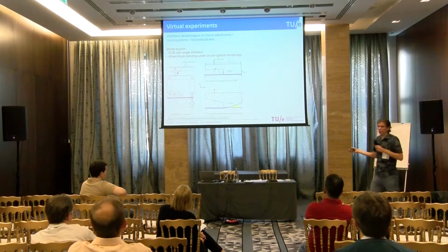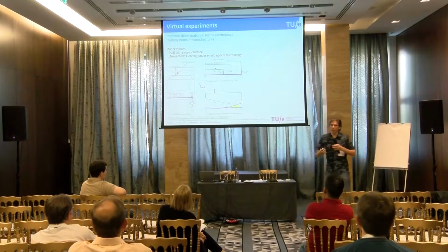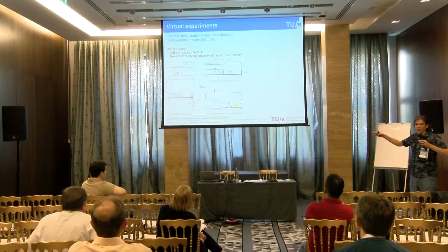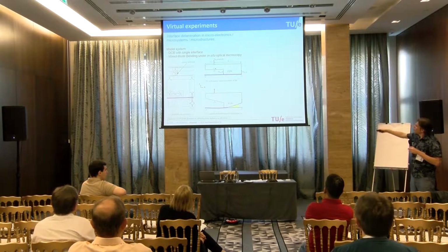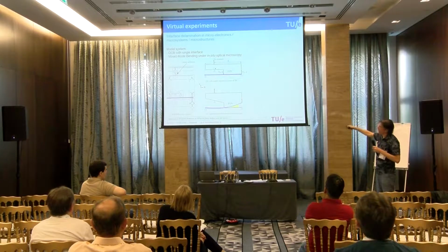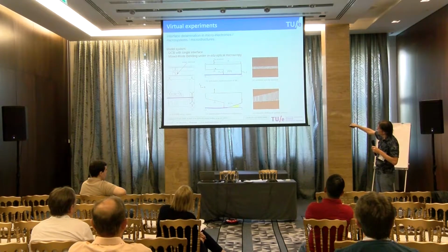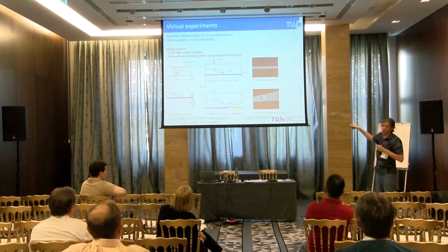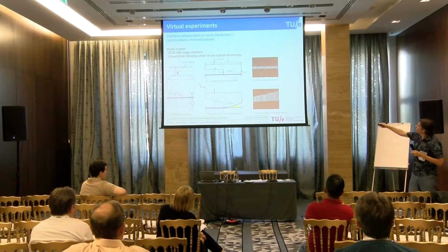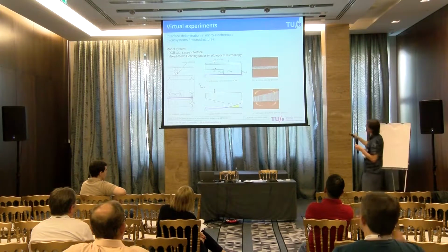Now, we're also going to do numerical modeling of this. First, we're going to test our framework in a virtual experiment. We're going to simulate the whole setup with a cohesive zone in there, and we simulate these kinds of images, as if we had really taken these with our microscope. We generate images like this: this is undeformed, this is deformed.